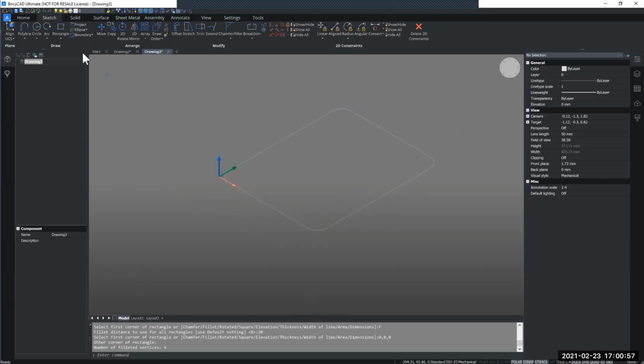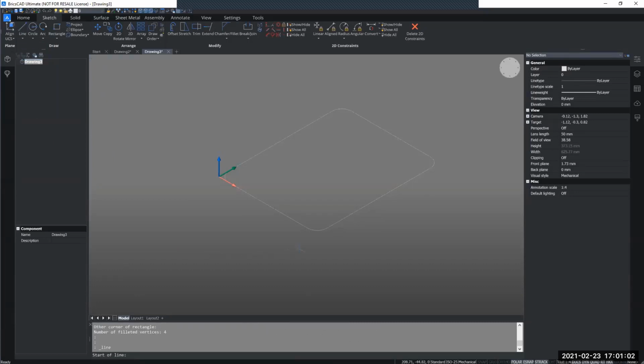In step 3 of surface modeling, it is asking me to draw a line to create a specific boundary for my model. This line should go from the endpoint of the radius here over to the other side and the endpoint of the radius here. So a straight line across the model here to create this boundary. Once I have this boundary, I can use the DM extrude command.